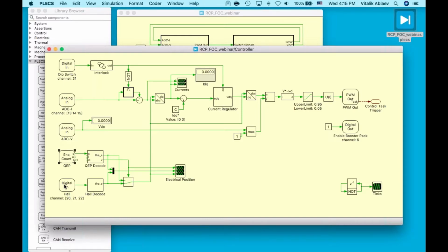Lastly, we're taking advantage of our Hall sensors, which come with the BLDC motor, to provide an approximation of the rotor flux angle before the motor receives its first index pulse. These Hall sensors are 60 degrees accurate, so we can quantize our theta waveform into 6 levels and use that information before we get our first index pulse from the encoder. Once that happens, the model will automatically shift to using the flux angle coming from the encoder rather than from the Hall sensors.